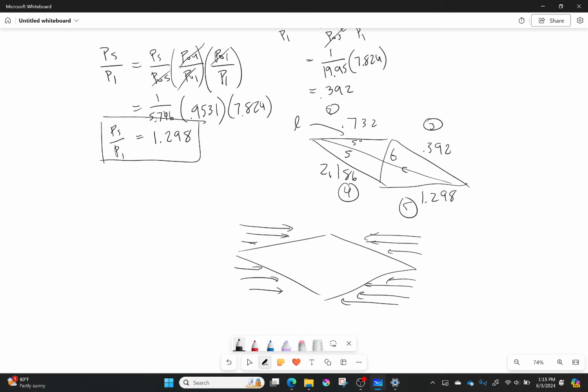And as a note, we'll call this the tangential force. Technically, this is like drag with zero angle of attack, but I'm going to fix it later, and I'm going to have the normal component as well. Those are not equal to lift and drag because it's at an angle of attack. I have to take that into account later, but it's a lot easier if I just pretend there's no angle of attack and then correct it at the end. So I'm trying to figure out that T force, tangential, going tangent to our direction, and then our normal force, going normal to it.